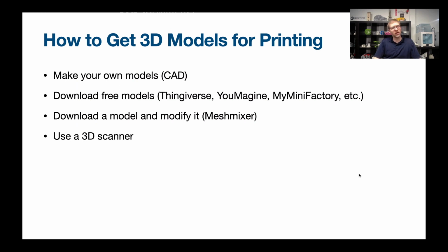You may need to do a little bit of cleanup on it before you 3D print it, just to clean up the scan mesh a little bit and remove any unwanted bits. But then you can clean it up and you can 3D print it and essentially make copies of that object for yourself. It's also helpful to use a 3D scan as kind of a reference to then build your own clean 3D model around. So you can 3D scan something and then just use that to build your own model around, so you have nice clean surfaces and clean geometry that you can use instead of relying on that mesh.